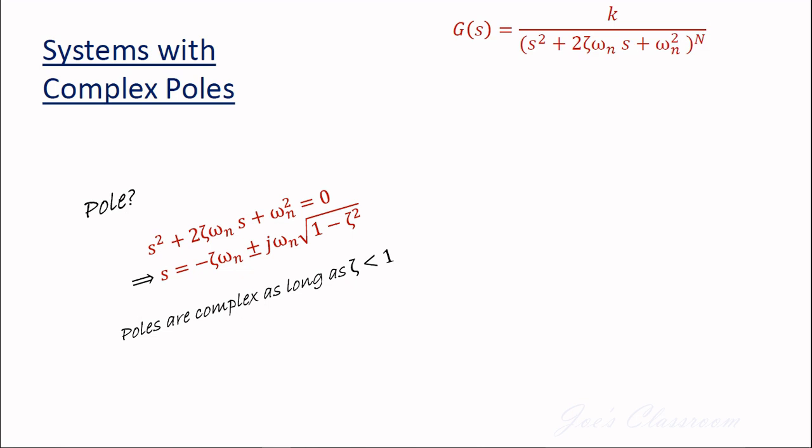In the previous discussions, we understood that the transfer function has to be expressed in time constant form. To express this transfer function in time constant form, this constant term should be 1. So if I want to make this 1, this omega n square has to be taken out of this entire term.